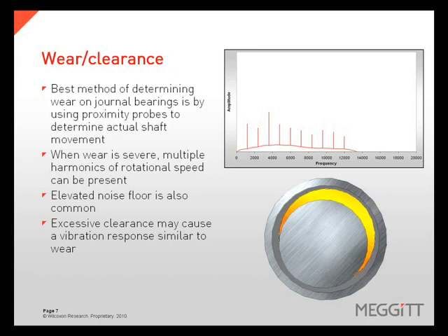When wear is severe, multiple harmonics of rotational speed will be present in a vibration spectrum, which is often accompanied with elevated noise floor. Excessive clearances will exhibit a very similar vibration response.